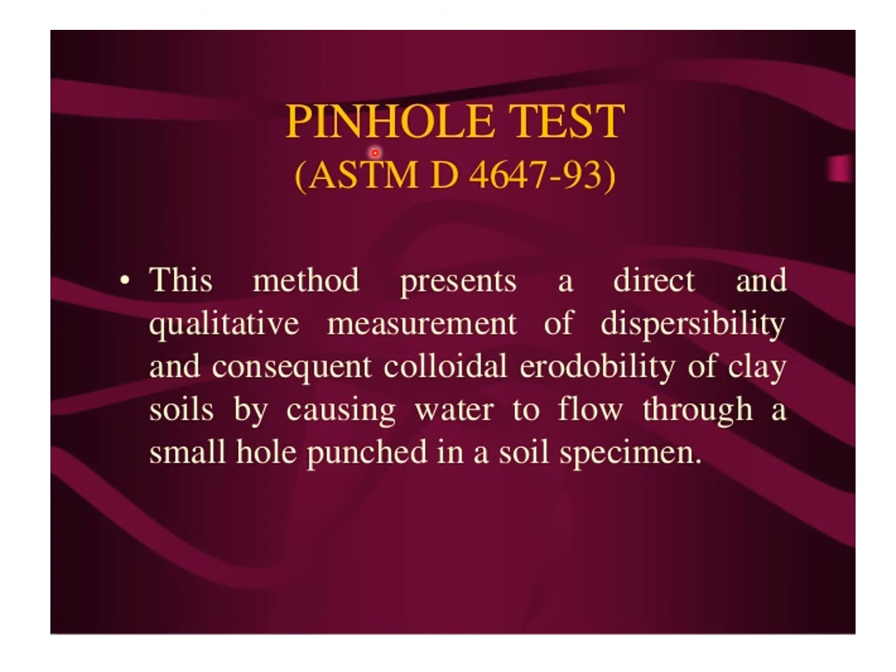Then comes pinhole test. This method presents a direct and qualitative measurement of dispersibility and the consequent colloidal erodibility of clay soil by causing water to flow through a small hole punched in a soil specimen.